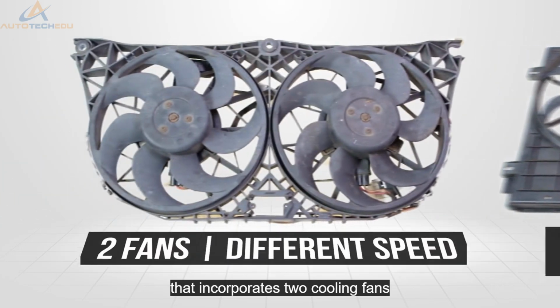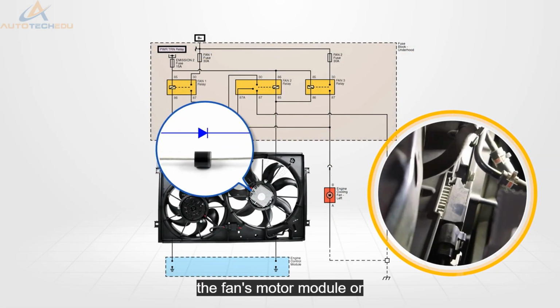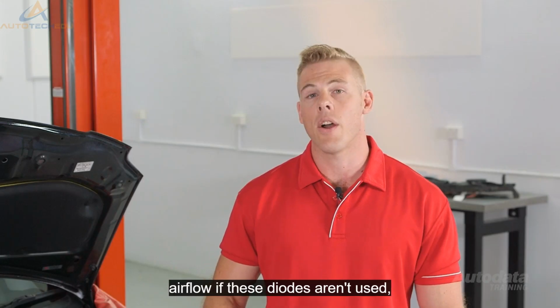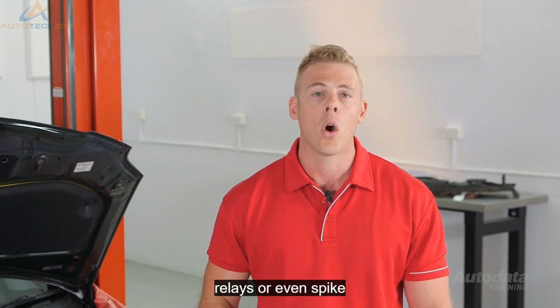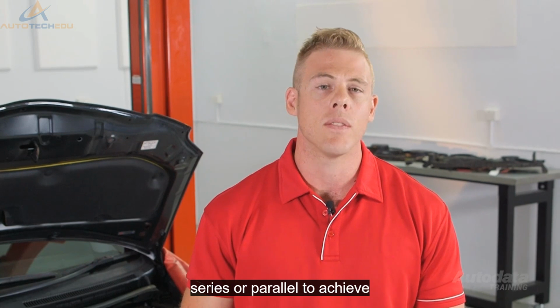A cooling system that incorporates 2 cooling fans that operate at different speeds will use electric motors with different operating wattage outputs or dissimilar fan blade diameters. Suppression diodes may be installed in the fan's motor, module or relays. When not in use, they eliminate any generated voltage from the fan motor when turned by the incoming airflow. If these diodes aren't used, the generated voltage may affect the correct operation of the relays or even spike the ECM. A system using 2 normally open relays can be wired in series or parallel to achieve low or high